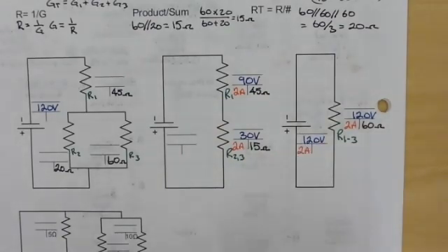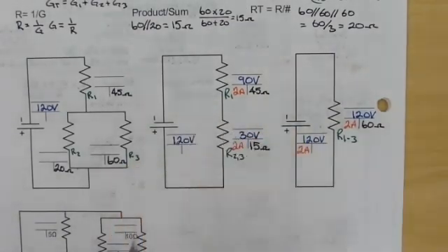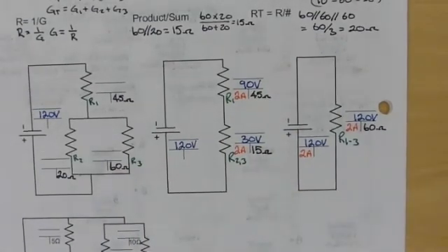Volts across this. Our source is still 120 volts. Kirchhoff's law states that any potential difference has to be shown in the circuit, so there are no missing voltages. Any potential rise would be a potential drop in the circuit. So 90 and 30 equals 120. Right back.